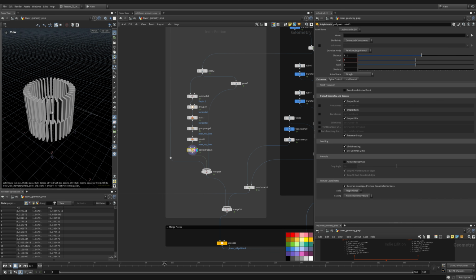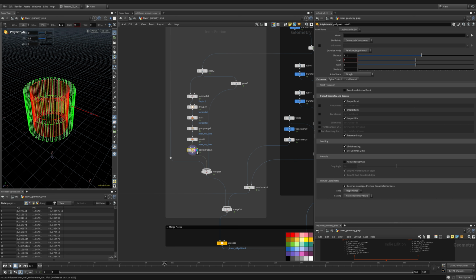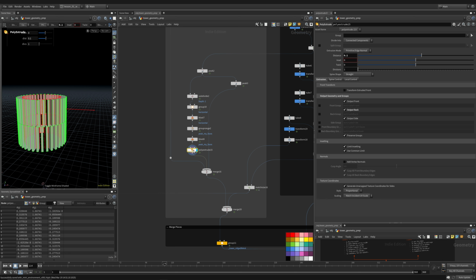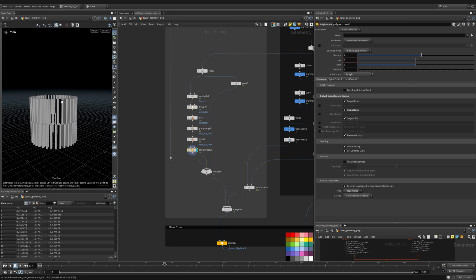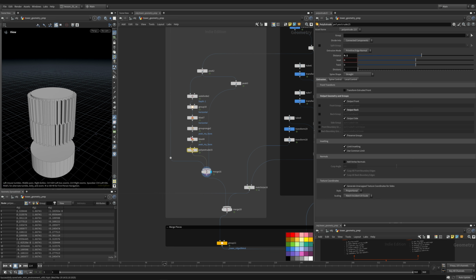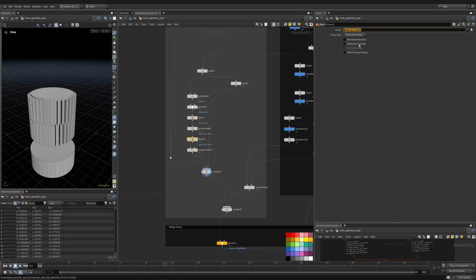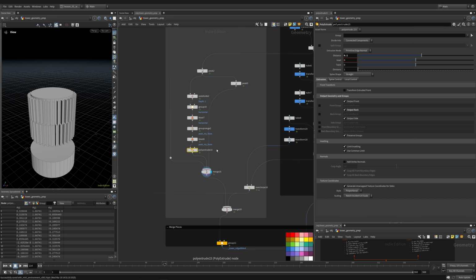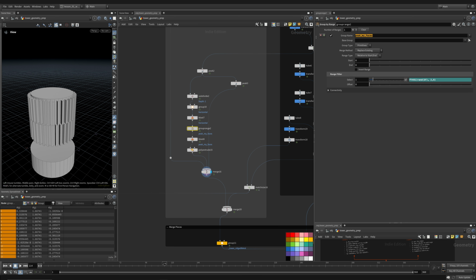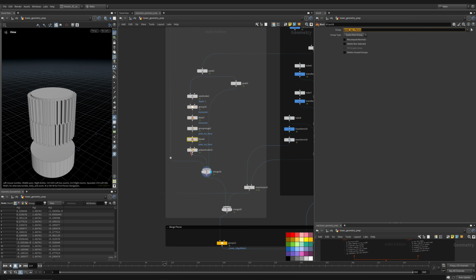And the reason I changed the names of the groups is to show you that the names are not intrinsically recognized by Houdini. So you can change them to whatever you want. And some names are, like P-scale and N and V. Those are important to Houdini. But in some cases, such as here, you don't actually need certain names. You can do whatever names you want. It's just keeping the names consistent between these two nodes that is important.